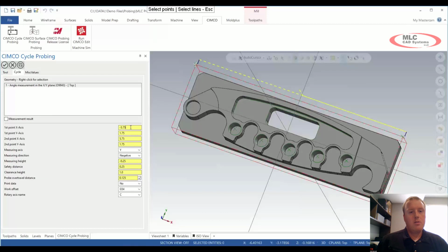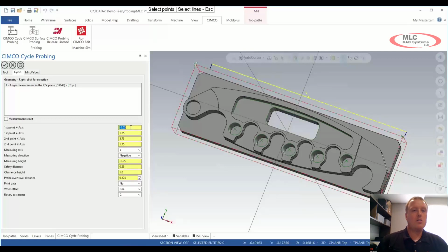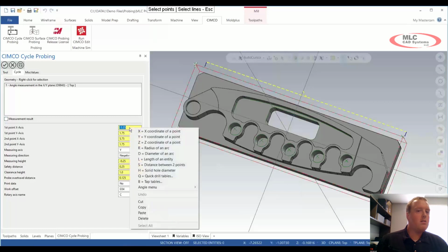With that, what I can do here is I can actually take my center mouse wheel if I want, and I can simply bump up my center mouse wheel, and each rotation or each little click of my center mouse wheel is going to move basically like 100 thou there. And that's going to allow me to then simply adjust based on where that probe hit is going to be. And then of course that's in live time showing me where that tool path is actually going to go ahead and do its thing. Now, if you don't want to necessarily use that, you could certainly type in a value.